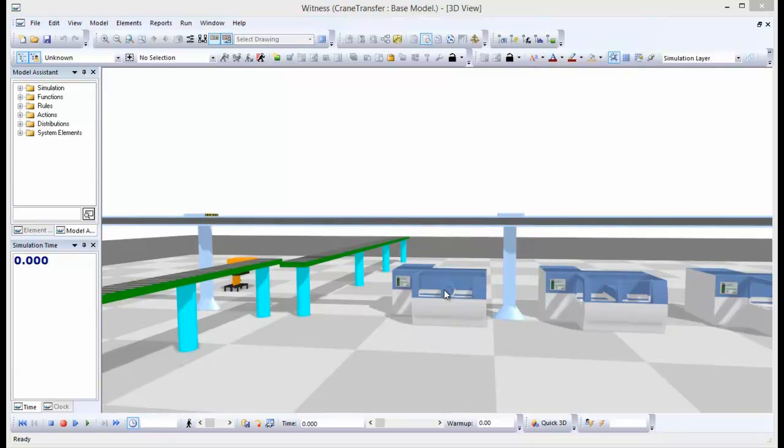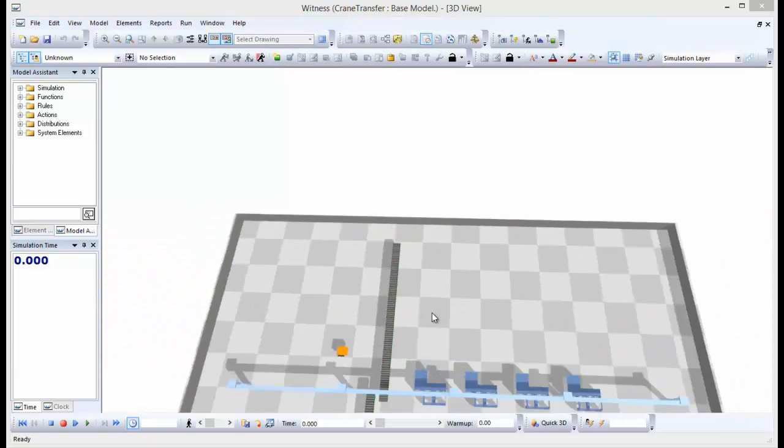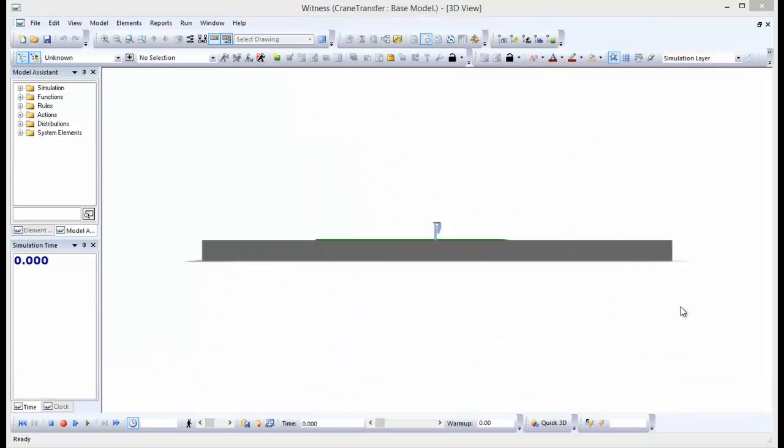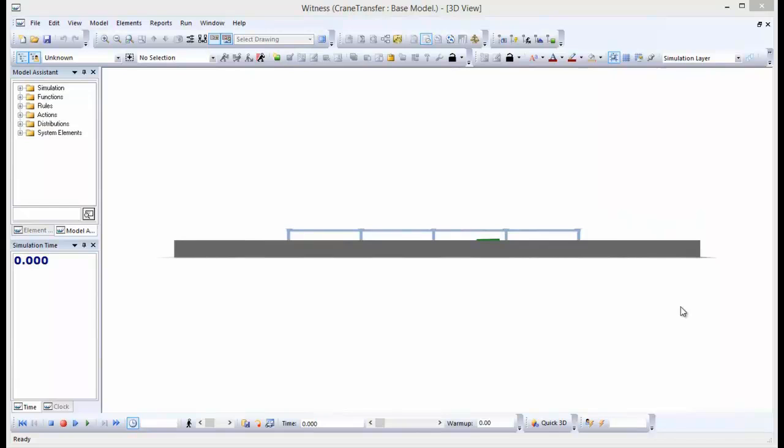If we move to the number pad on your computer, and having clicked in the view once, if I press the number 5 key, you will see that I've gone to a vertical view, pressing that number 5 key. If I then go to a number 4 key after clicking in the view, I will go to one particular orthogonal direction. It's 2 key, 6 key and 8 key. They all go to the different orthogonal values. Not so useful when we have kind of walls in the way like this.